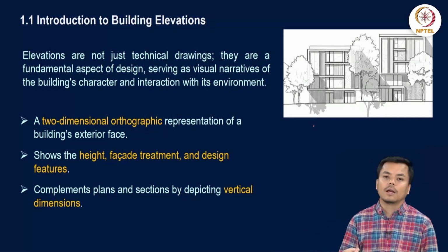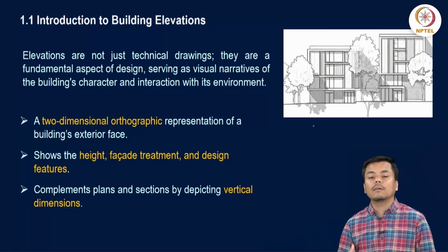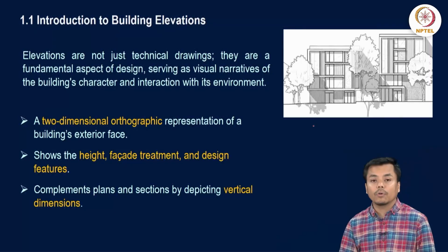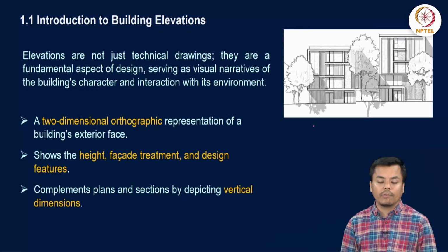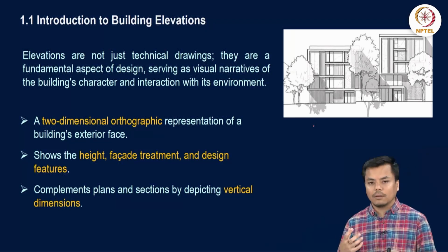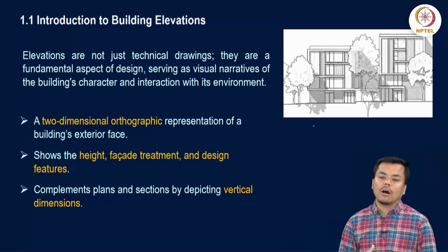And the information with respect to cardinal direction, like if you mention it is your north side elevation or if it is your south side elevation, then probably that specific mention of the cardinal directions will help you also in designing the elevation, because generally in the Indian case, especially near the equatorial, near the tropical line, and mostly in central India or southern India, we follow one specific approach that our southern side should have minimum exposure, that is minimum openings present in the southern side and western side, so that we don't allow the high exposure of our structure from the southern side or western side.